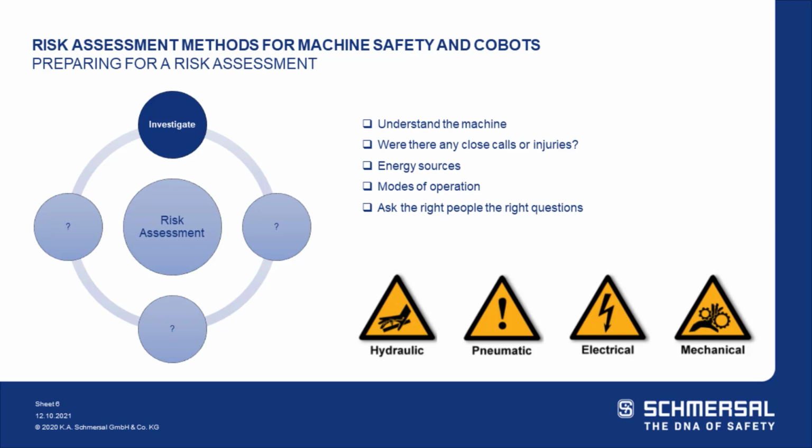So now, if the machine is new, and it's being built by an OEM, the machine builders here today, take time to think if some of the tasks are realistic or it's something that you could see yourself bypassing, right? A lot of times working for an integrator, you're asked to do things and you're saying, does this sound realistic? Are they going to have people bypass it? Because when we make it too safe or bulletproof, it causes bypassing. So we have to find that balance, right? Again, for the machine builders, have you built a similar machine in the past, right? If yes, do you know what is currently being bypassed on the machine? So maybe it's something to investigate further for future design.